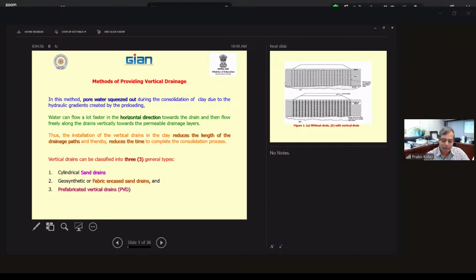All right. Again, welcome back. The last session, consolidation, was a lightning session, correct? I know everyone knows it, but I covered it quickly because it is in the syllabus. The consolidation test is very important. With a simple consolidation test, you can find out so many parameters: av, mv, cv, degree of consolidation, and then you can find the settlement. It depends on what type of clay you are using.